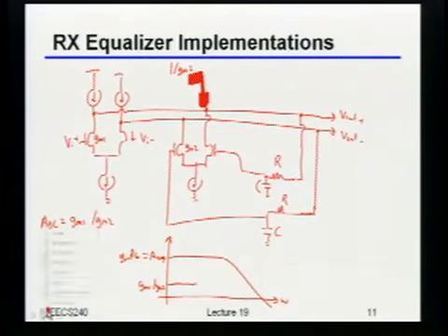In other words, what's going to happen is you're going to start to get something that does, well, let me draw that a little bit better. Let's start doing this, right? So that's just 1 over RC here. Okay, so now what would happen? There's sort of 2 things that we need to keep in mind here. First, we know that the amplifier by itself has a finite bandwidth, right? So clearly, I'm eventually going to have to get a pole just from the amplifier by itself. But actually, I'm going to pick up another pole. That other pole is just coming from the following thing.